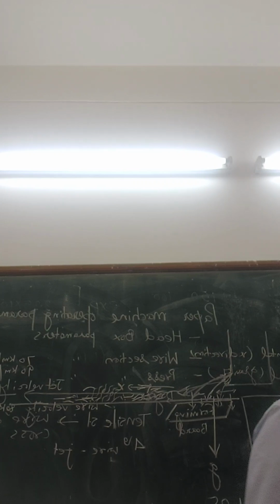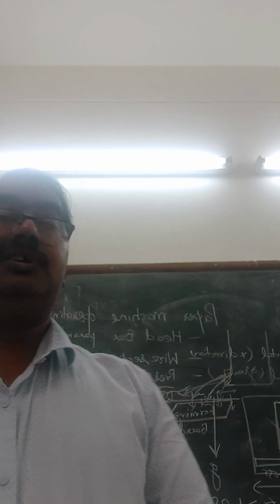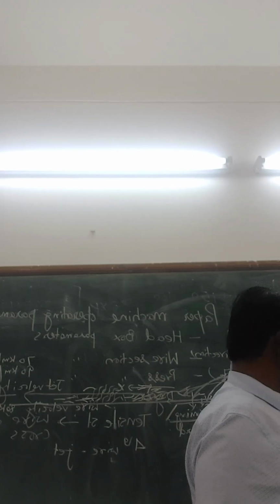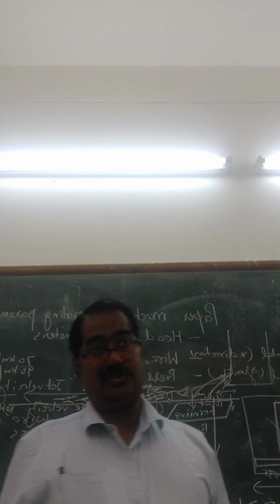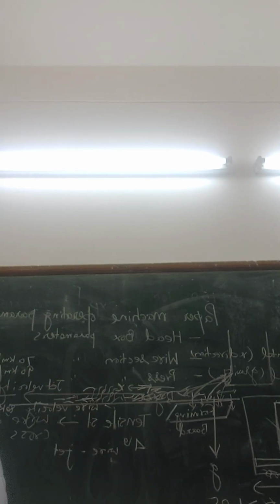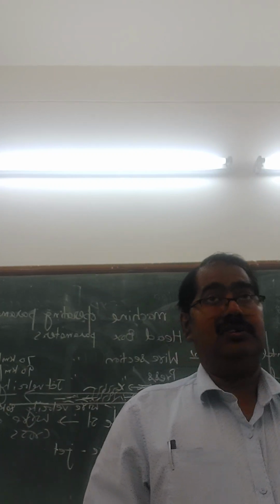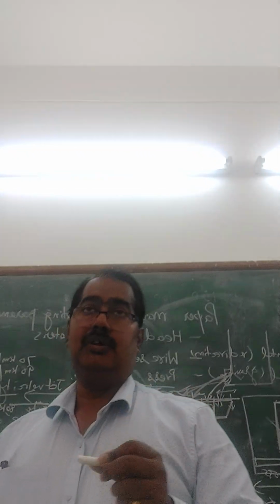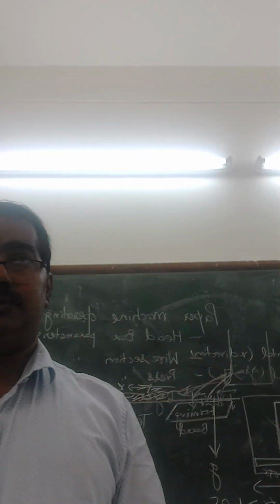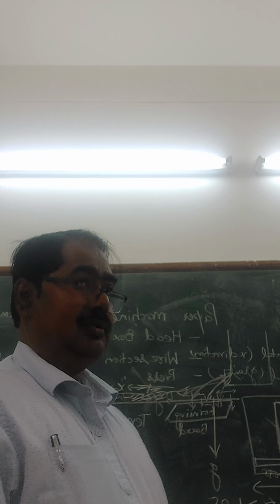In optical properties, we have the brightness and opacity. If more fibers are in some location of the paper, the opacity will be more there. At some points opacity will be higher, at some points lower. That is again the negative aspect of the paper. Right? So in this way, from the headbox you can control the strength properties, again the optical uniformness of the brightness and opacity, and formation. Right? See the second point.